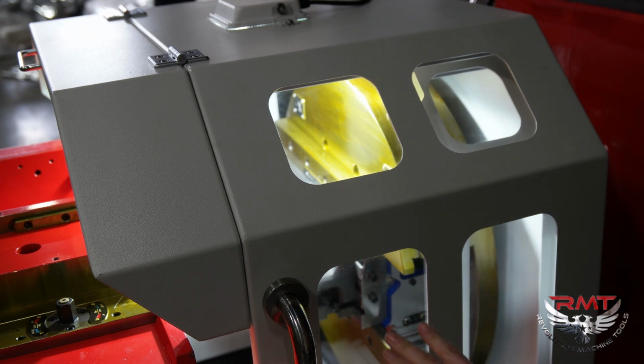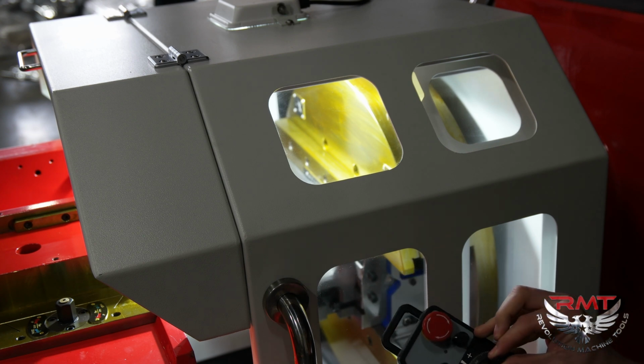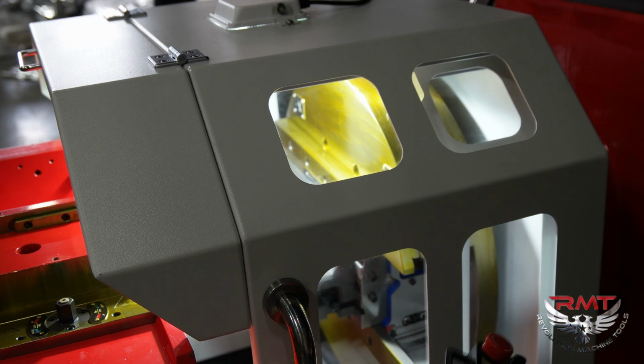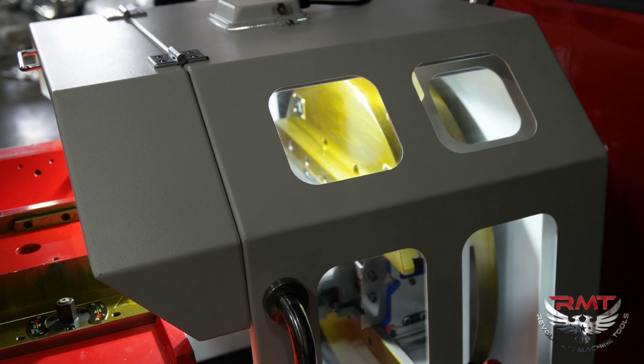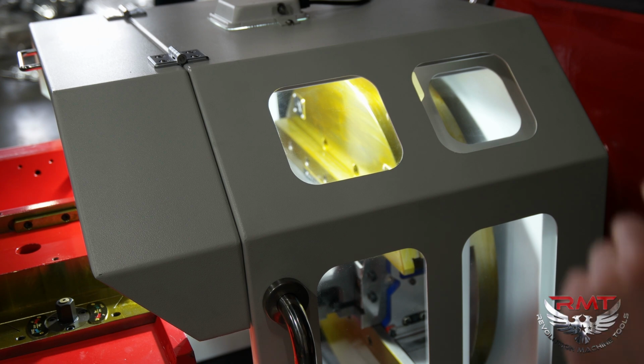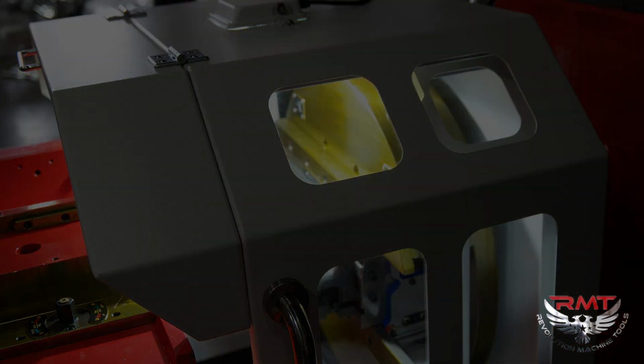But from here, I would just turn on my spindle in the correct direction for cutting, and just slowly start to feed in X on my jog box until we start to hear it just make contact, very lightly. We don't want it to sound too interrupted. That means that our vise isn't centered, but it should be a nice, like, smooth sounding cut that doesn't sound too interrupted.